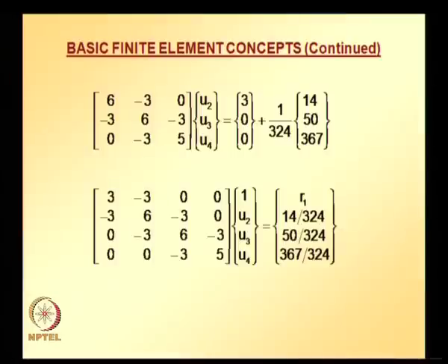During derivation of the functional, this term was neglected with the stipulation that only admissible functions will be considered as trial solution. Thus, the right hand term corresponding to the known nodal value is actually unknown. Therefore, the correct form of the global equation after imposing the boundary condition is given here.